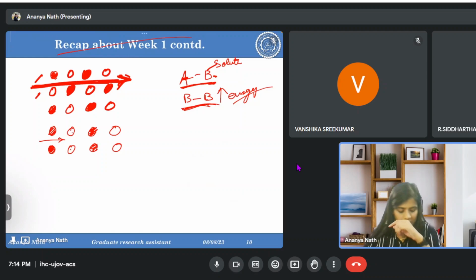But apart from that, this type of scenario is called the antiphase boundary, because different or opposite type of atoms are facing each other. So antiphase boundary also has its importance in this particular topic, because it will provide again a difficult situation for the dislocation to move further. So this is how we are again disrupting the path of the dislocations.